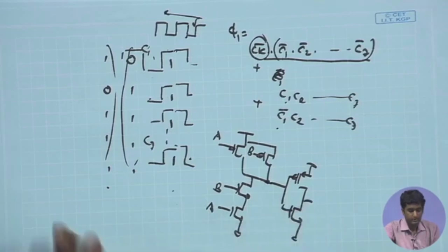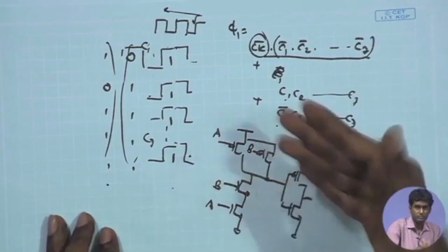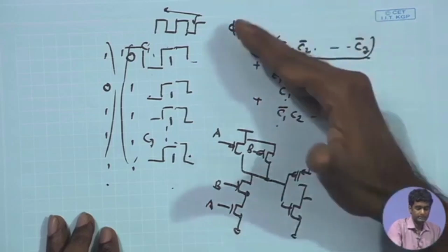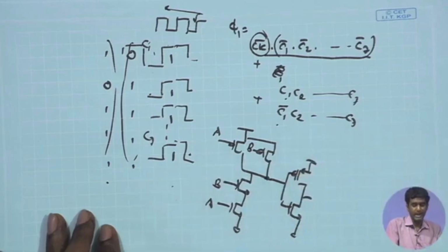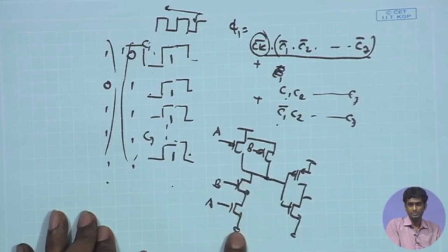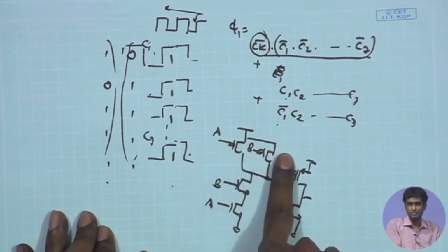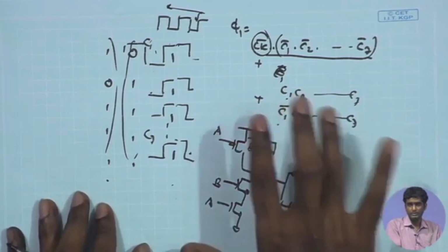So, this is AND gate. Now, if you want to implement this function over here, can we go on adding? So, if I go for 3 input NAND gate or 3 input AND gate, I just need to add another C over here, the third transistor coming over here and another third transistor in the parallel.